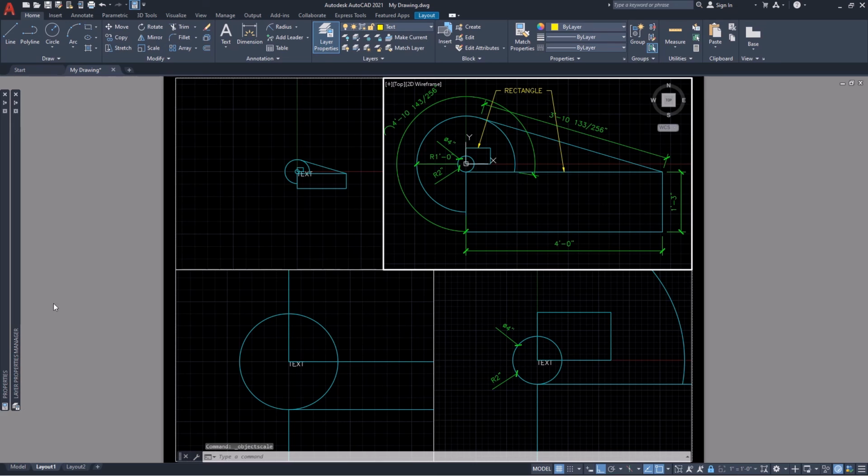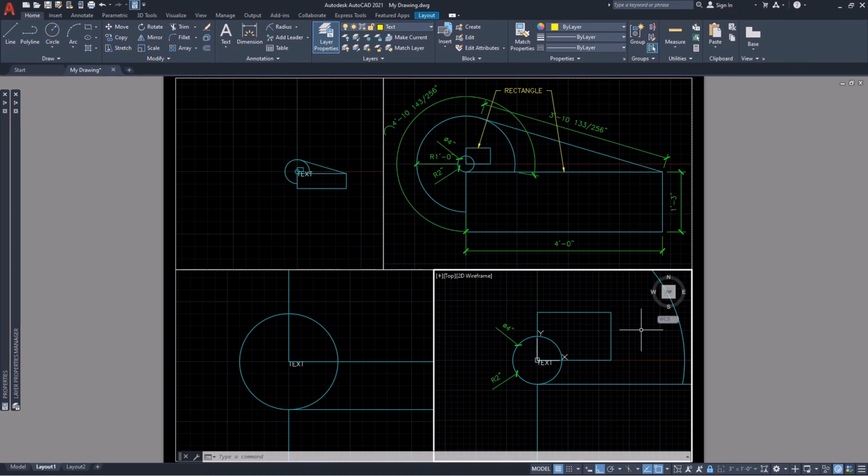These two dimensions now display in the lower right viewport window. Note that the small rectangle has not had any dimensions applied to it to this point. Left-click one time inside the lower right viewport window to switch active viewports. Verify that the dimension layer is the current drawing layer, either in the Layers panel at the top of the display or in the Properties panel.